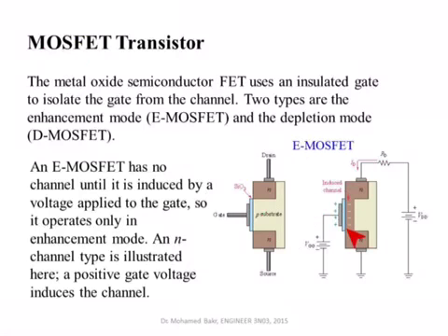Where do these electrons come from? They came because of the voltage applied to this capacitor. This really is a capacitor. There is a metal electrode here, and there is a channel, so the electrons get attracted to the positive field that we have there, and this creates this conduction channel. Of course, the width of this conduction channel can be controlled by the gate to source voltage. It's like any other capacitor. And by reducing the gate to source voltage, we can reduce this conduction channel and thus reduce the current that can flow from drain to the source.